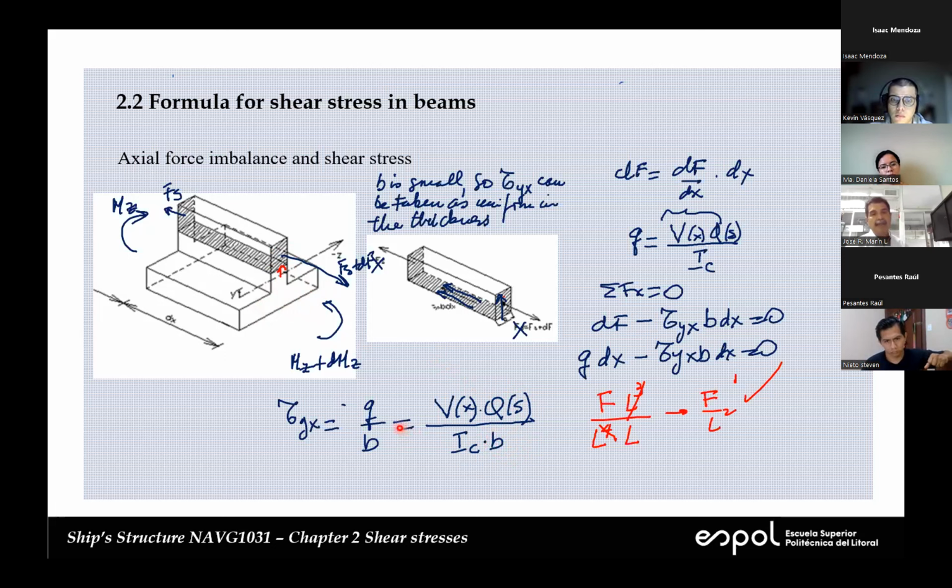And that's why usually what we do is we work with the shear flow. At the end, when you want to calculate the shear stress, you consider a certain position. From the plot, from the sketch, you get the shear flow, and you simply divide that by the thickness at that point, and you get the shear stress. And we do this because we can check that our calculations are correct, because this parameter, the first moment, is a continuous one. That's the explanation, okay?